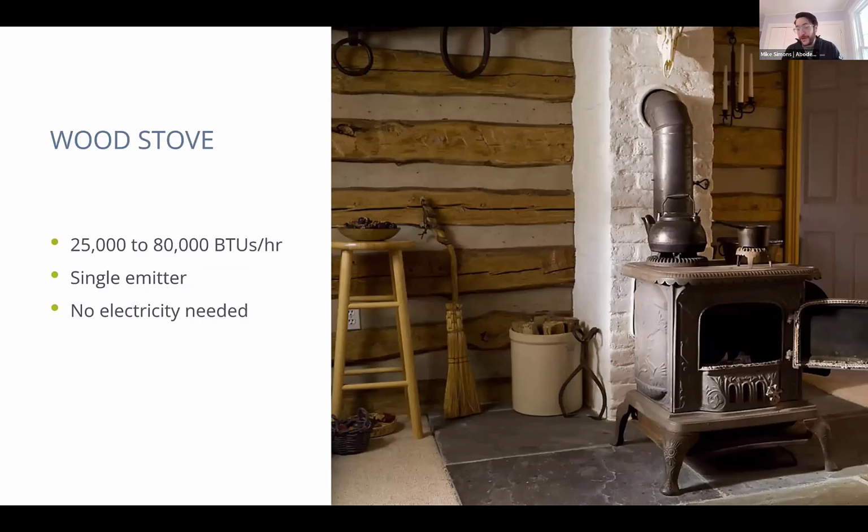And the better thing that they created was a wood stove. The big thing with a wood stove is it gets the firebox out of the chimney, which allows for convective loops to happen. So if we were following my mouse, let's say cold air is denser than warm air, and warm air is more buoyant than cold air. What would be happening over on the floor is that there's dense cold air. As you're heating up the wood stove, it's going to heat up the air that's below the wood stove, and make it hot and buoyant.